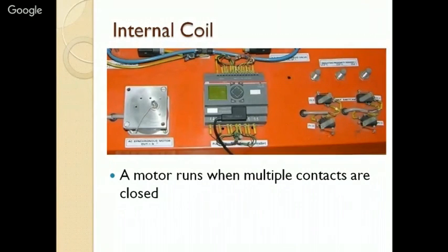For example, in automation, in a totally automated factory, an AGV may come to a docking station of a CNC machine. So when the AGV docks, there is a sensor which tells that AGV has docked, and then AGV may be carrying a raw workpiece. So another sensor will determine whether the AGV is carrying a workpiece. Machining may be already going on in the CNC machine. So we need sensor inputs to come to know that machining is complete. And then if the machining is complete, a robotic arm or a manipulator has to unload the workpiece from the CNC machine, put it on the AGV, pick the component from AGV, put it on the machine.